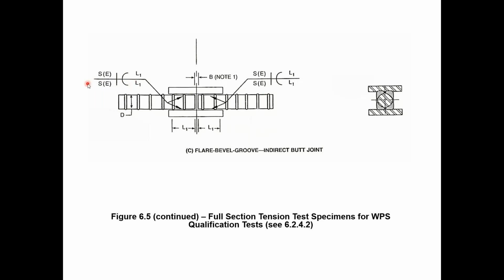If the information is only on the bottom, so if there was nothing on the top of this symbol, that would mean you're only having to weld where the arrow points. Because you've got an arrow pointing here and an arrow pointing here, and the symbol goes on the bottom and the top, it's telling you it's required on the visible side and the blind side, so on the near side and the back side. That's why when you look at this section, you see it here and here, even though this was invisible in the view before.